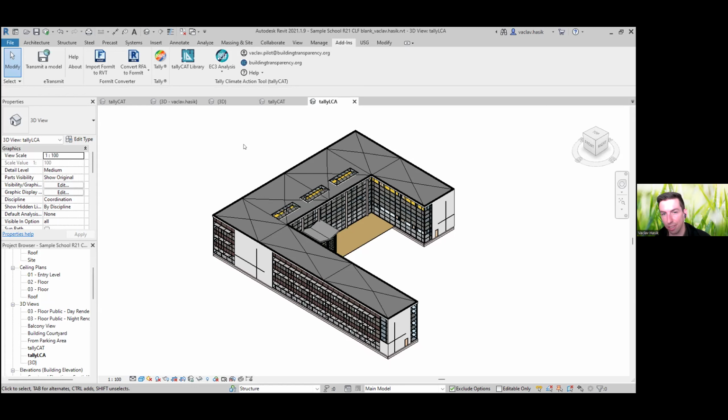The reason is because EC3 focuses just on the global warming potential category, and it does have some ways of actually also comparing the specificity of the various EPD results. It's a different and much simpler topic, or slightly simpler topic, of aligning results from EPDs for the global warming potential category versus all of the environmental impact categories that are listed. There's generally much more alignment in the methodology behind the global warming potential estimates.